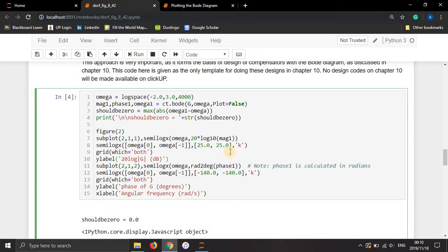So I just want to show you a quick trick that I've actually only learned recently. If you click here and you're holding control and then you click again, you can edit in two places at once, and you can do this as many times, 5, 6, 7 different places. So those we want as zeros, and we click away. Then you hold control and you click there, and we want these to be negative 180. Okay, and you click away to get rid of it.